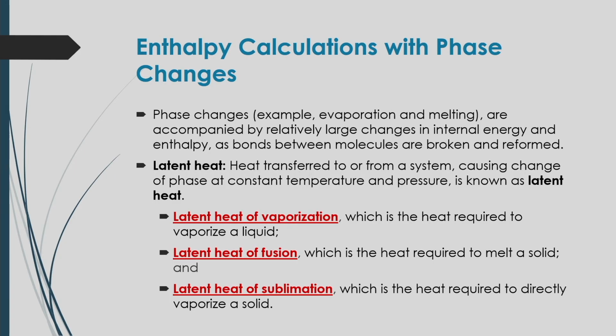are accompanied by relatively large changes in internal energy and enthalpy, and in that case you have to refer to the change of heat or change of internal energy. That heat change gives you the enthalpy change at a constant temperature for changing its phase from one to another. So, that heat of change of phase is called latent heat.